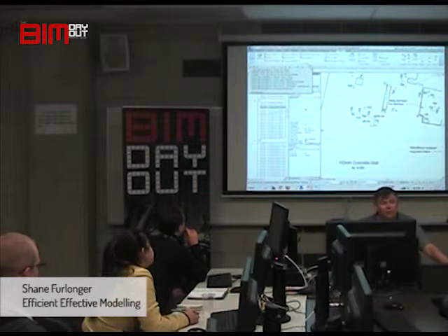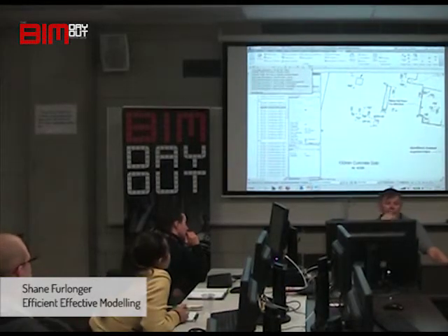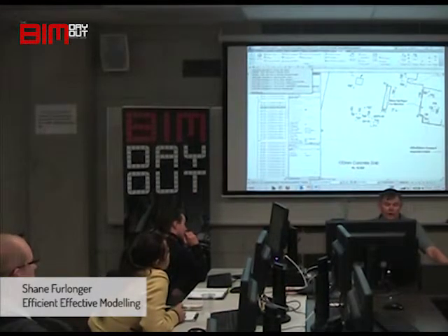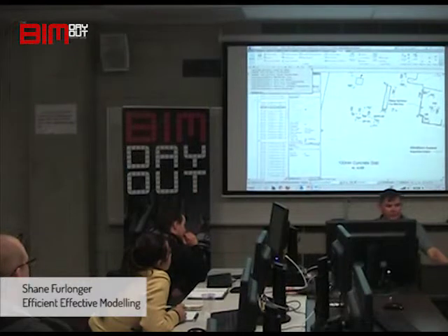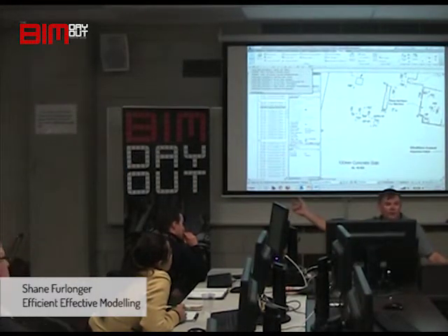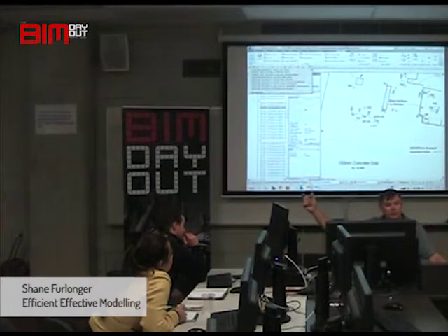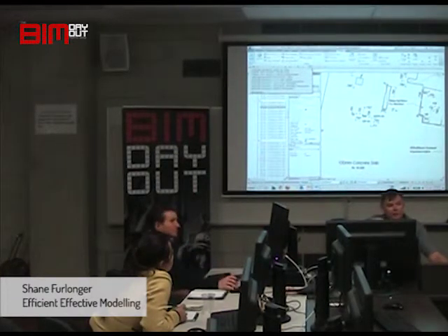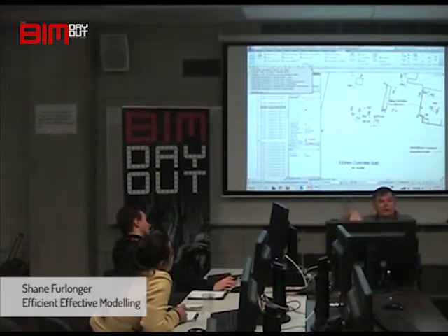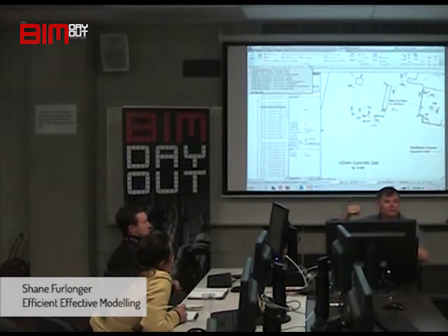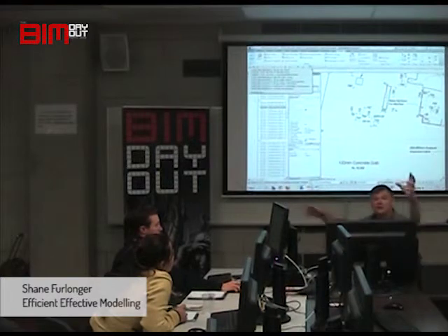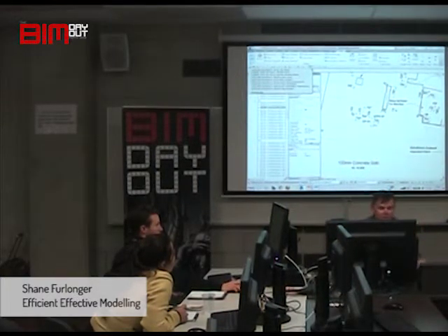If you're not worried about taking any elements off your model, like knowing how many bricks are in your project, then you could just stick it off to one side of your model somewhere, out of the way. Mind you, every time you go to spin your model, if you haven't clicked on an item, it's going to take the centre point of everything and rotate around that. So you're going to see this thing every time you want to rotate unless you crop down, so that can be a bit of a pain.